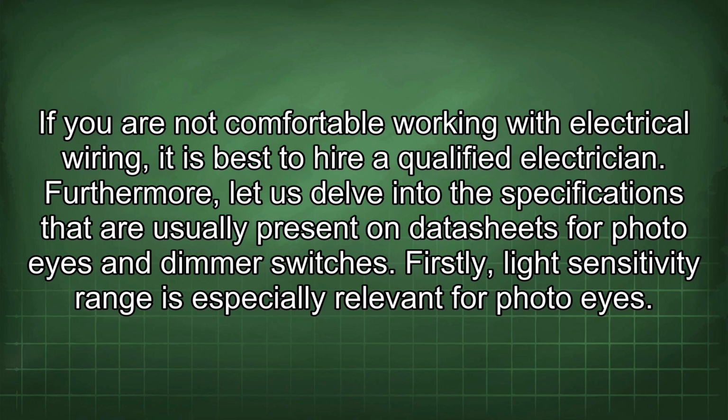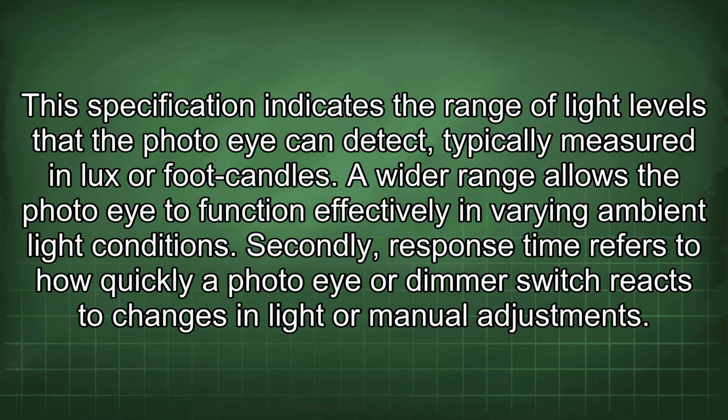Furthermore, let us delve into the specifications that are usually present on datasheets for photo eyes and dimmer switches. Firstly, light sensitivity range is especially relevant for photo eyes. This specification indicates the range of light levels that the photo eye can detect, typically measured in lux or foot candles. A wider range allows the photo eye to function effectively in varying ambient light conditions.